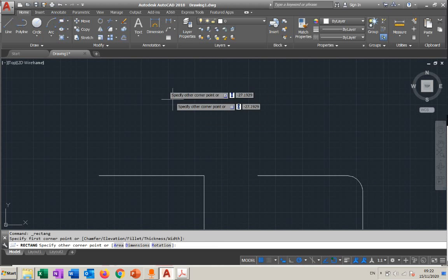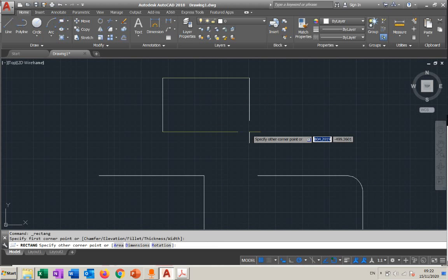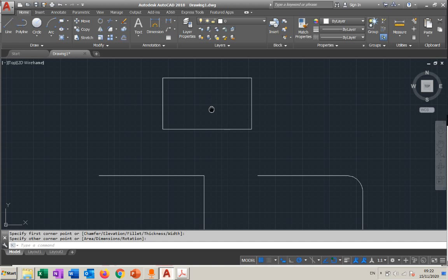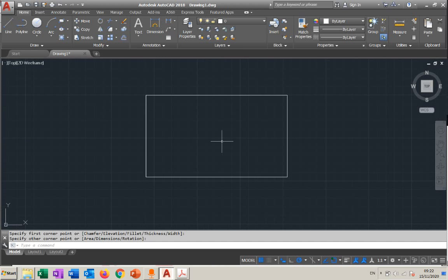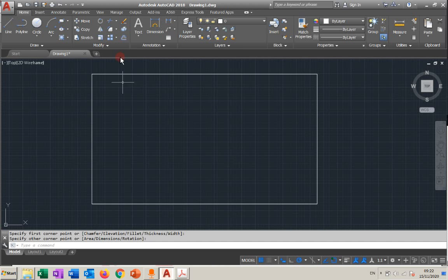If you have a rectangle, let's say this rectangle, it's 400 by 800. Let's say I have a big rectangle. I'm just practicing something. Now I will activate fillet. Now the radius is 0. I'll click on the radius. Let's say I'm gonna reuse radius 10.